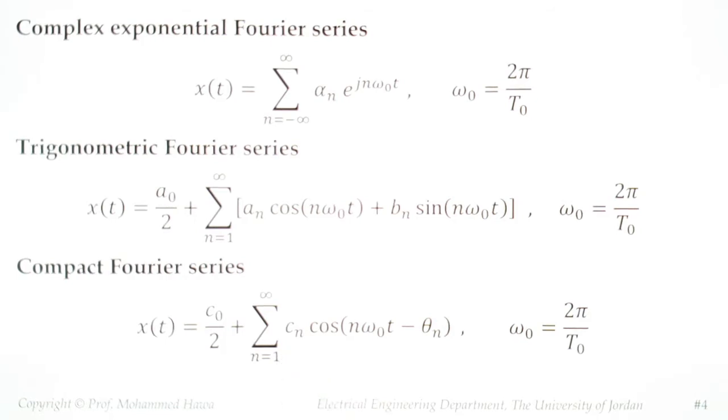You start adding cosines, cosines, cosines. What are the differences between those cosines you're adding? There are three differences. First, the frequency keeps changing. The first cosine has frequency omega naught, the fundamental, and then the next one has 2 omega naught, 3 omega naught, the fourth one 4 omega naught, 5 omega naught, 6 omega naught, and so on.